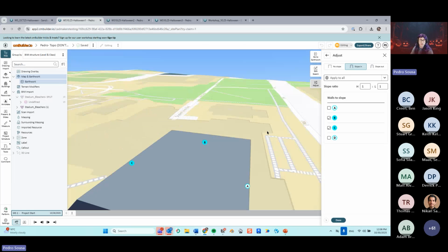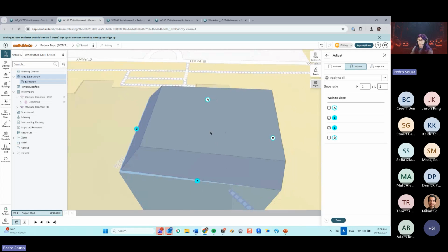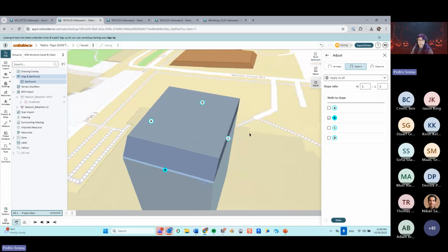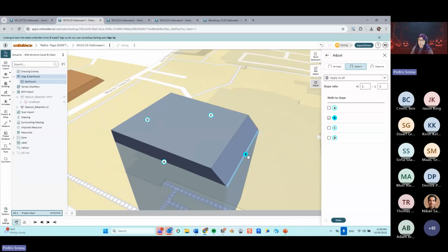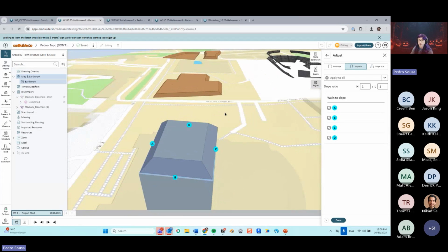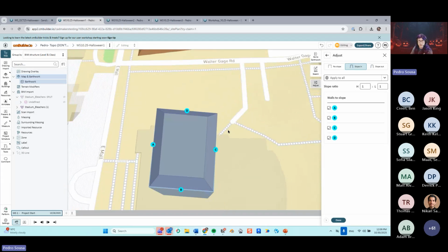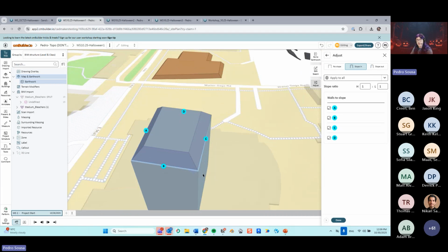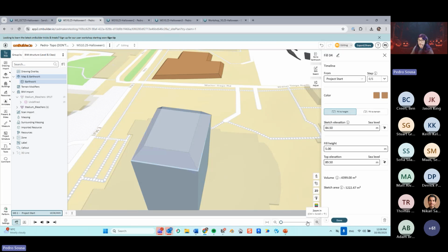Now you can also deactivate and activate specific faces for different sides of your excavation operation. This is a quick one, but it's quite important, especially for people who have more complex earthwork operations to represent. Before, you had to create a cut to remove a slope that you didn't want, but now you can select them directly from here.